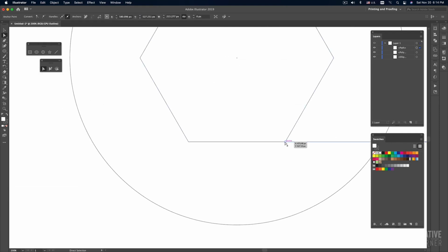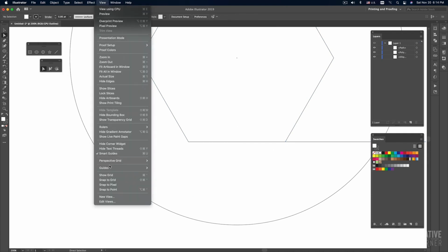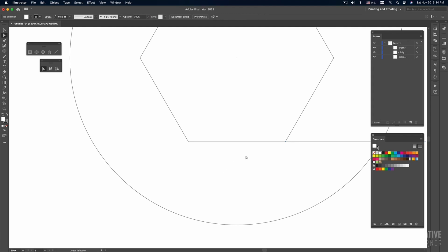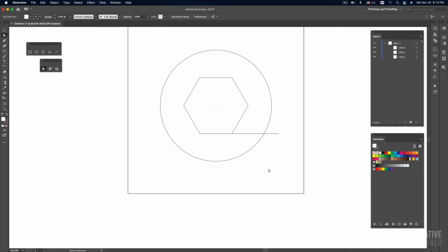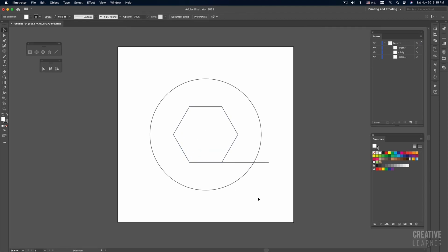In Illustrator, if you are not sure of the touching thing because of the view, we have smart guides. Because of that help, I can easily build my touching point in Illustrator. So the snap guide is helping us. If I bring it down like this, it is not snapping. If I get closer to it, it will snap. Even though my mouse is here, it will automatically snap to the point. That is a good thing about Illustrator. After that, I have drawn one projecting line, the extra to our circle.